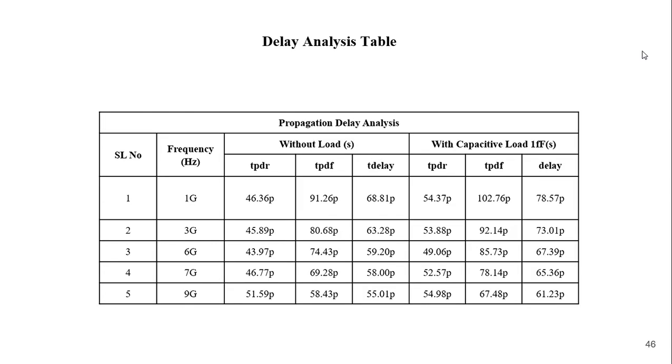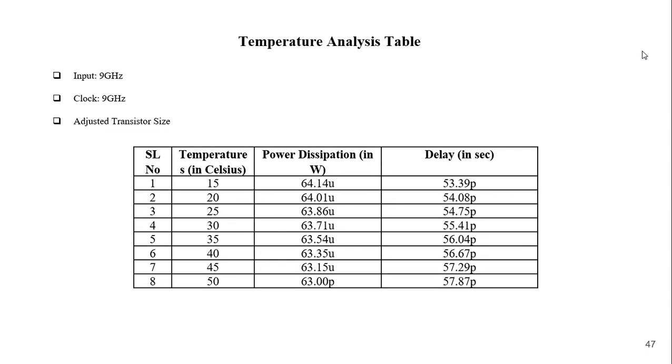Delay analysis, yeah, this is also done at 9 gigahertz. You can see it's good with 55 picoseconds, though it is a bit higher than design 1, but still it has fewer transistors. Temperature analysis again shows how good it is even at higher temperatures.